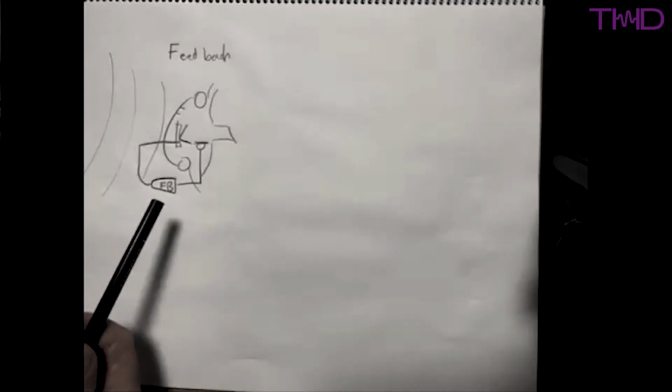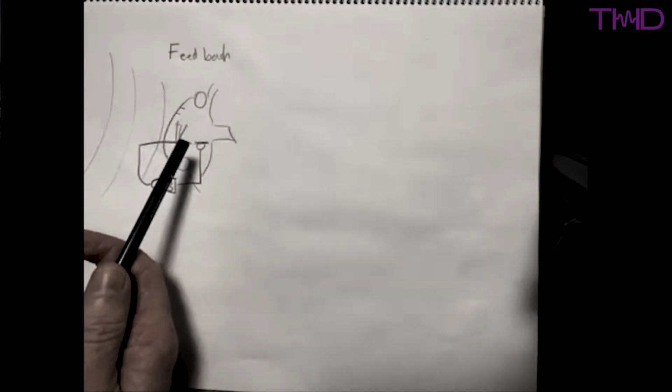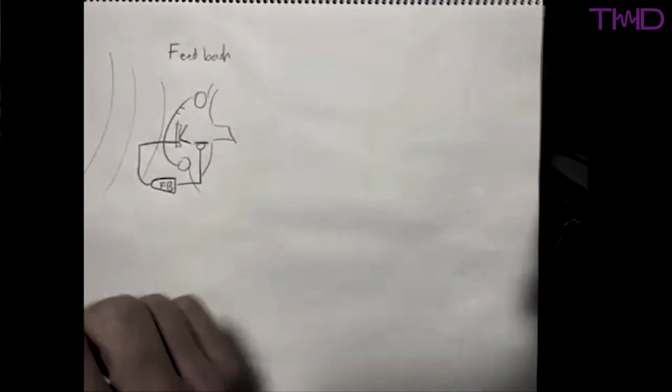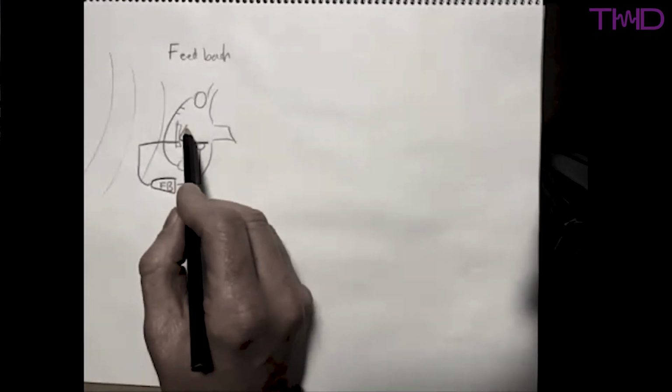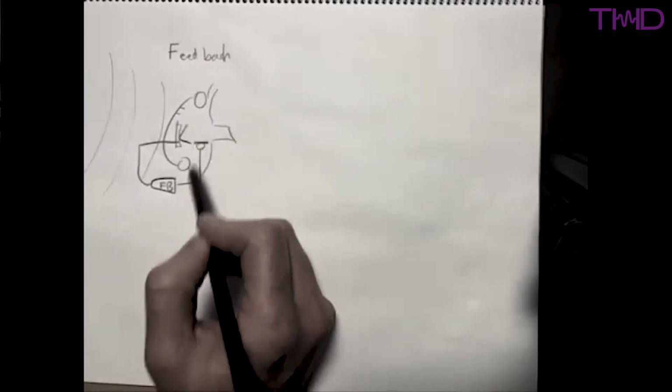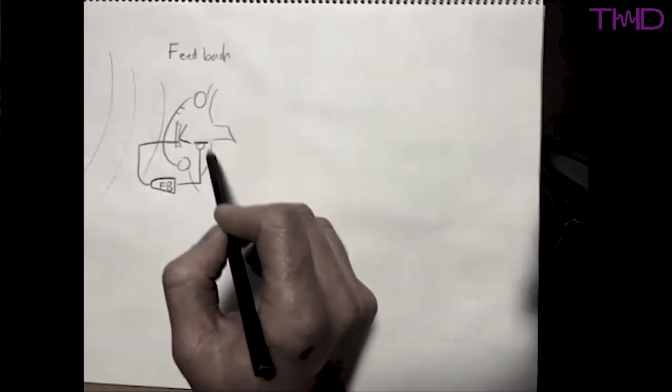Okay. Yep. If we just take this case where there is no audio, and we can add the audio in a minute. So the speaker is trying to generate an opposite waveform to whatever that microphone is picking up. What it means by feedback is that whatever signal that speaker puts out is also picked up by the microphone. So there's actually a loop of the pickup and the speaker.